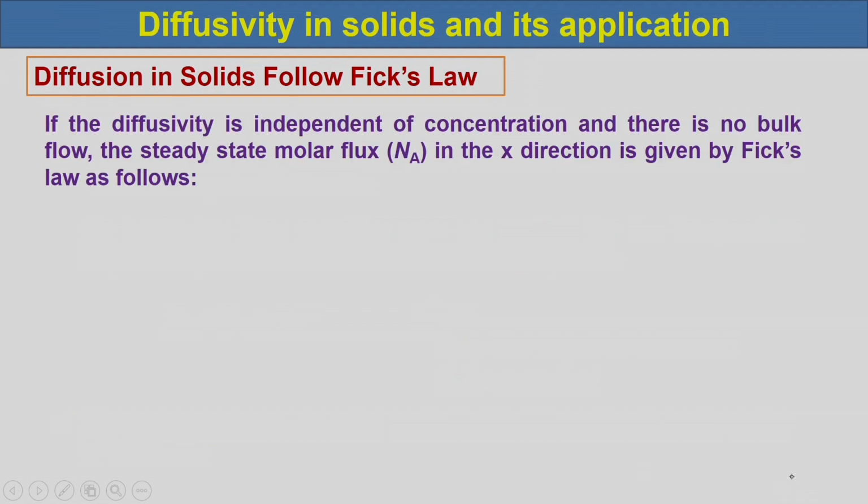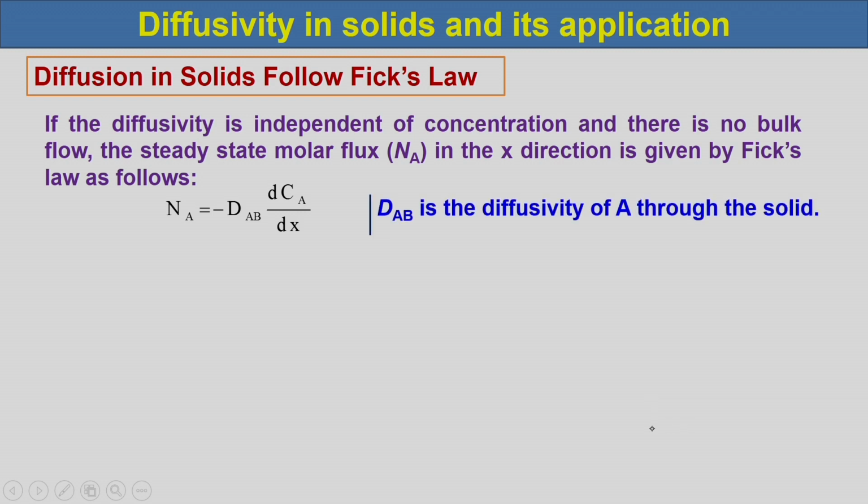Now, if the diffusivity is independent of concentration and there is no bulk flow, the steady state molar flux N_A in the x direction is given by Fick's law as follows: N_A equal to minus D_AB dC_A/dx. Here D_AB is the diffusivity of A through the solid.